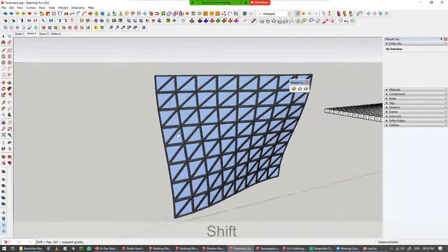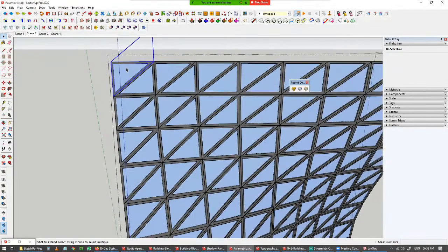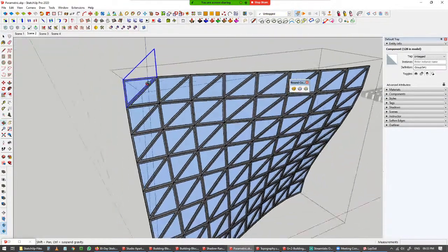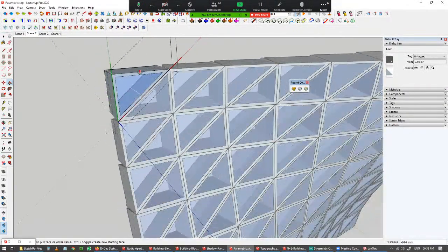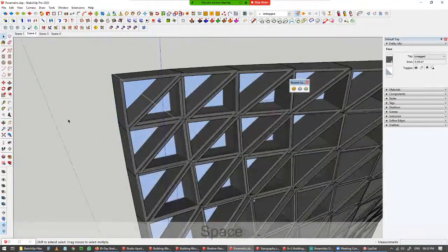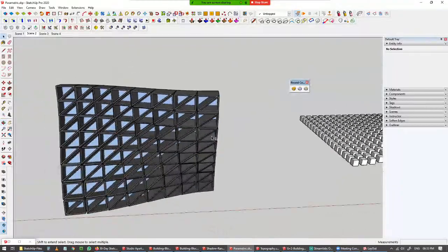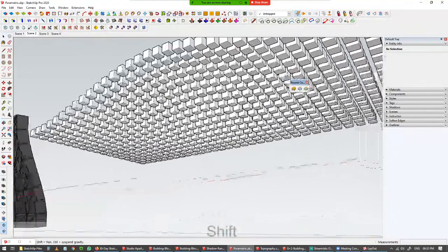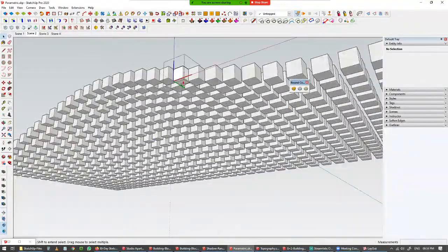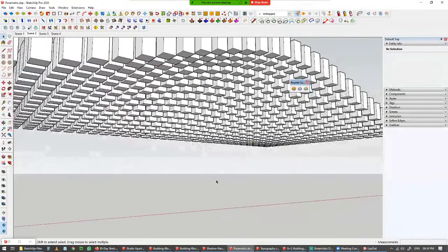Similarly, we can work on parametrics in elevations. Like here we have glazing, and if I make any kind of change in the glazing, all of them will be modified instantaneously, as they are all connected as groups, as components. And similarly, parametrics are also applied in false ceilings nowadays. So we can have different kinds of elements like these for false ceilings, maybe in the case of acoustical spaces, and so on.